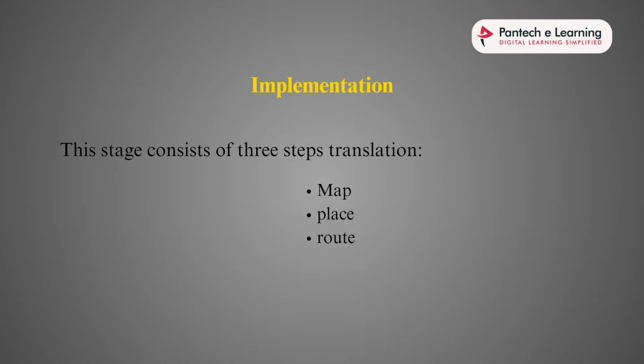The tool's initial step is to compile all the user-specified constraints along with the netlist files. These limitations may be related to pin assignment, locations, and timing specifications like maximum delay or clock input period. The implementation is then mapped out by the tool, matching the resources actually available on the FPGA against the resource requirements specified in the files. The whole process of mapping, placing and routing is fully undertaken by the tools. We just have to assign the IO pins and the clock frequency. FPGAs have lots of clock frequencies, so we have to assign the pins in the tool itself.